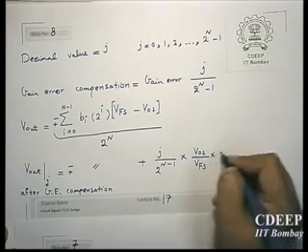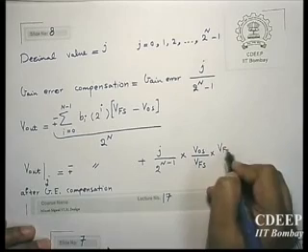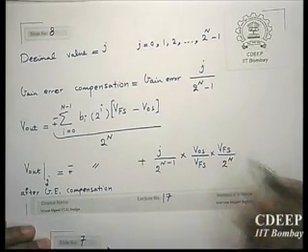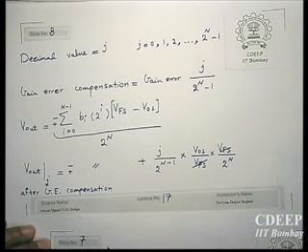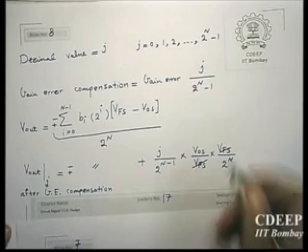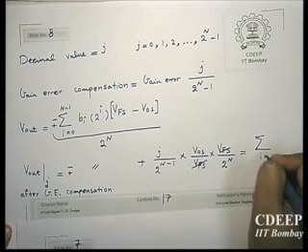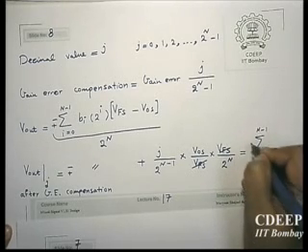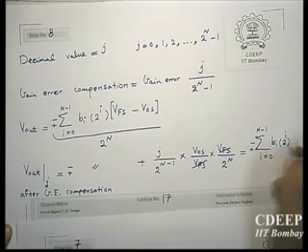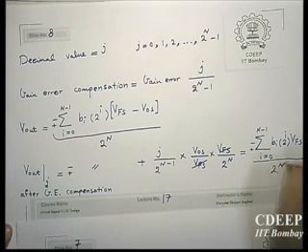If you want to get it versus absolute value, like here, we should multiply by LSB size. Therefore, now these two terms will get cancelled, and that is the reason the output after gain error compensation is equal to the sum of V_i 2 to the power i, V full scale upon 2 to the power n.